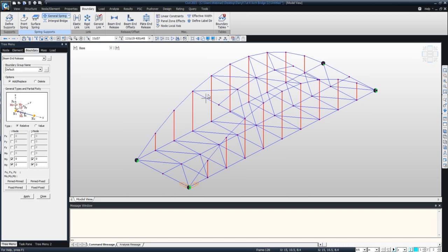And then you can just apply the beam element releases that you want, by clicking here. So you can do pinned, pin fixed, fixed pinned, etc. For this one, let's select partial fixity. So we'll just select fixed pinned, and then just click apply.